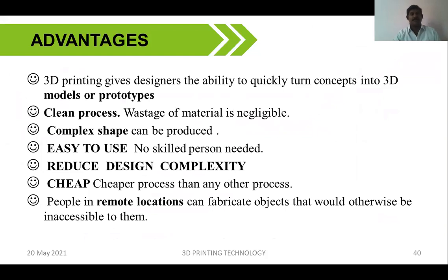Yes, let's see the advantages of 3D printing. Through this 3D printing technology, we can easily create models and prototypes, and it is a clean process. Wastage is very low when compared to a real-time manufacturing process. And complex shapes we can easily produce. No assembly, we can easily make the full structure. It is easy to use, reduces design complexity, and is a cheaper process than other processes. And in a remote location, we can easily fabricate the particular object. That is the major advantage of 3D printing technology.